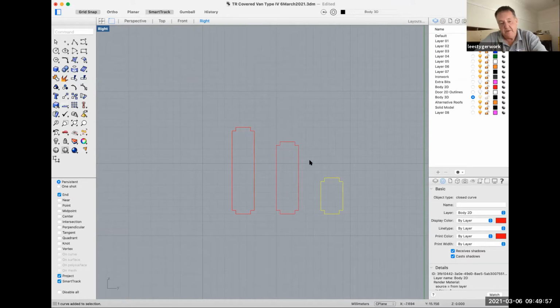And experience has shown that if you chamfer the edges of your planks to give the plank definition, or if you fillet, put a round on the planks to give plank definition, although it looks fine within the CAD model, when you print these things, often that definition can be lost.